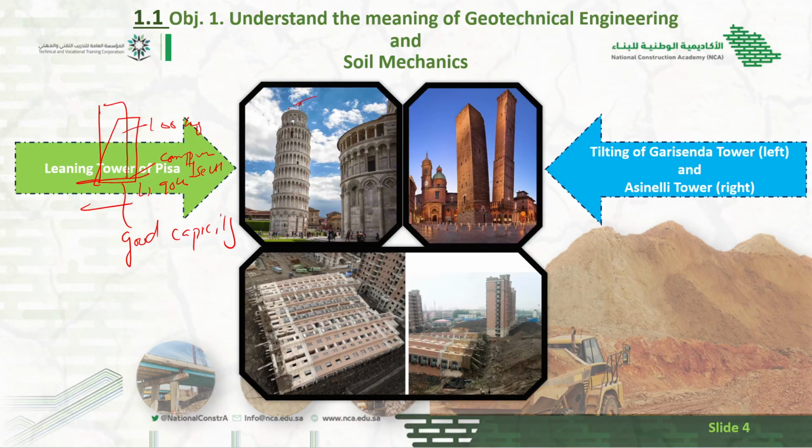But still you can see the building, the structural elements, beam, column, slab, are good enough to resist the gravity or lateral loads. The problem here is with respect to the soil bearing capacity. The bearing capacity of the soil is not enough to resist the upcoming load from the building. The remaining building is well enough because the structural elements are in their own position. It is not cracked or demolished, but the building overall is tilted, because of the soil under this building.